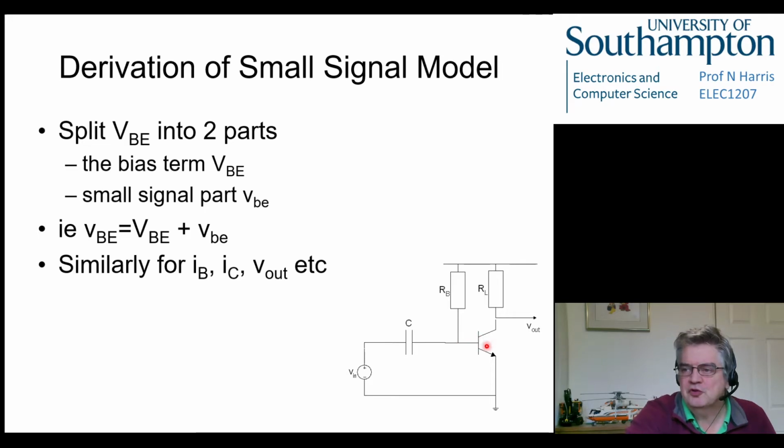So the current has to go this way and into the transistor, and we know that if there's a current being driven into a transistor here, we get another current through here, which is beta times bigger. So this means that for no signal coming in here at all, we've got a static condition. We've got a constant current going down here, which is defined by the value of this resistor, and we've got another constant current flowing through here, if we assume that no current can escape out of this point here, which is not connected to anything in this case, that's fine.